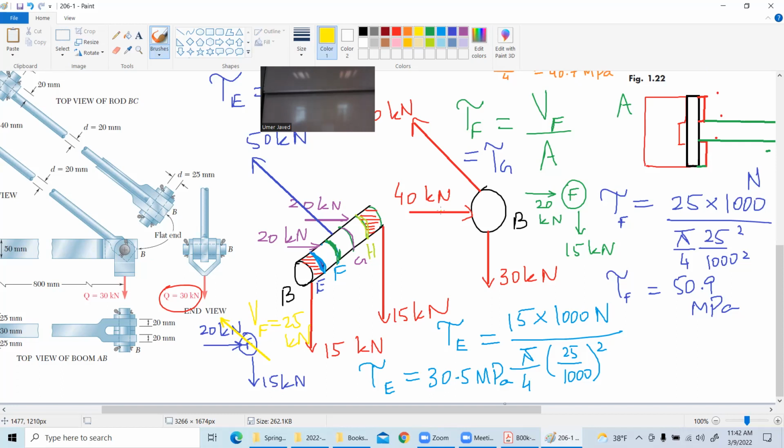Okay, I get it. And then one more thing. I thought to myself, why are the areas reversed? Because at pin A, we said that there is 220 kilonewtons and then 140 kilonewtons, because there are two pieces that are connected here, and there's only one. So there is 140 kilonewtons, so we have to have one area that is being applied. Why do we multiply by two? Okay, I will tell you. Show me the picture.